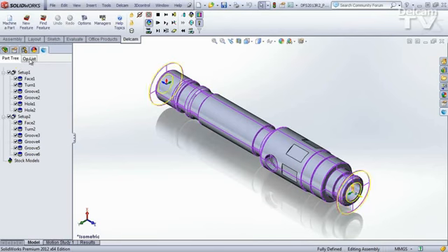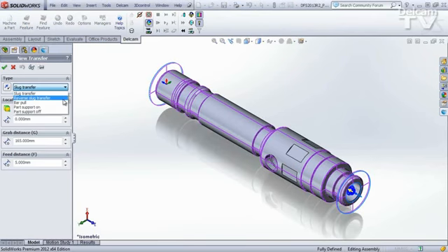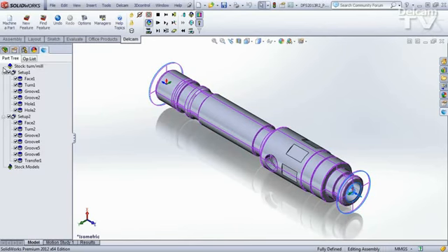Well, no more. Now you can go straight to New Feature, Part Handling, and you see the options I spoke of in the introduction. We have slug transfer. The location, I'll just grab off of the face of the part, and I'll grab distance of 165, so 165 millimeters from the front of the part, and click OK. And you can see this transfer down here in setup 2.